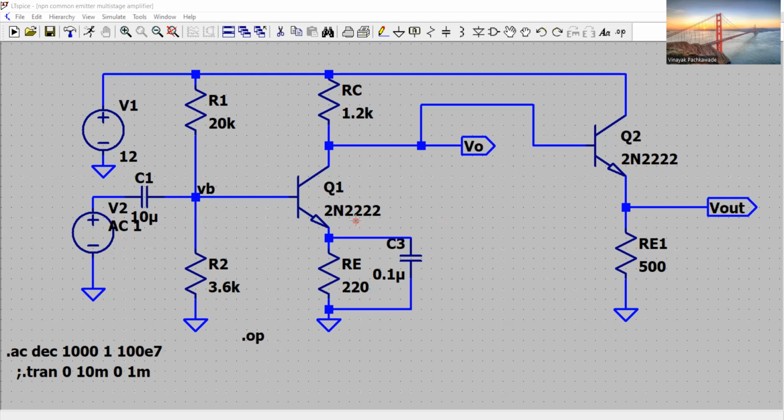But for this common emitter stage, the input impedance isn't ideally high enough, or it is high enough, and that's why we are using the external voltage source to drive it. However, its output impedance is not low enough to supply the high demand of current required by the loads.